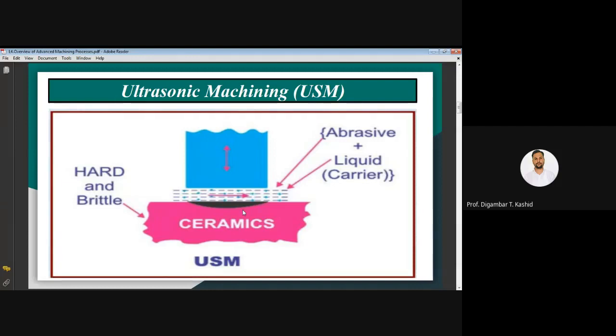Now, ultrasonic means what? Ultrasonic vibrations, or ultrasonic frequency. Because it is more than 20,000 hertz, that is called ultrasonic frequency. So using that ultrasonic frequency or vibration we remove the material, so it is called ultrasonic machining. I repeat, when the tool I have shown strikes the abrasive particles, the vibration means momentum. The particles get momentum from the vibration and strike the workpiece metal.